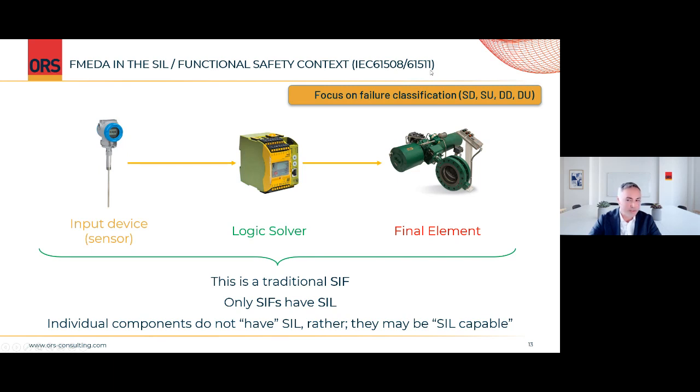One part of the standards relates to demonstrating that the components, what we call safe subcomponents, for instance a transmitter, a relay, or a programmable logic solver, are reliable. The supplier of the components must prove that they can be used in safety instrumented systems. And how do they do it? Again, this is also well established in the IEC standards.